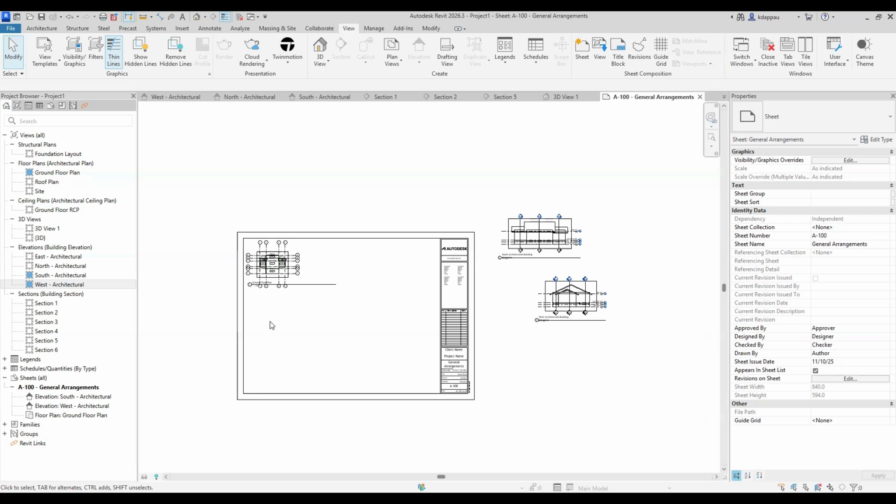No, you shouldn't be restricted, because as we move along, we have general arrangement drawings, we have detailed drawings, and even with the detailed drawings, we have enlarged views, component details, assembly details, subcomponent details. So depending upon the kind of view you are putting on the sheet, that will determine the scale at which you are going to put it on that sheet.